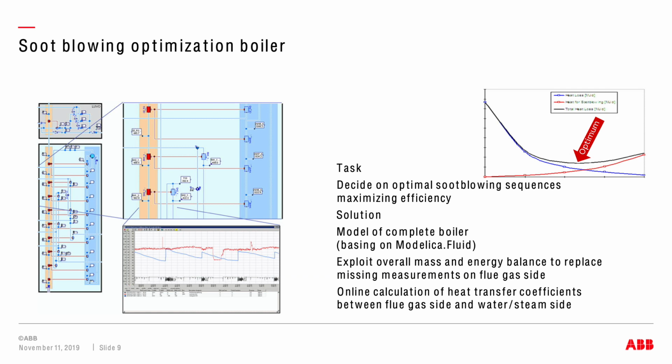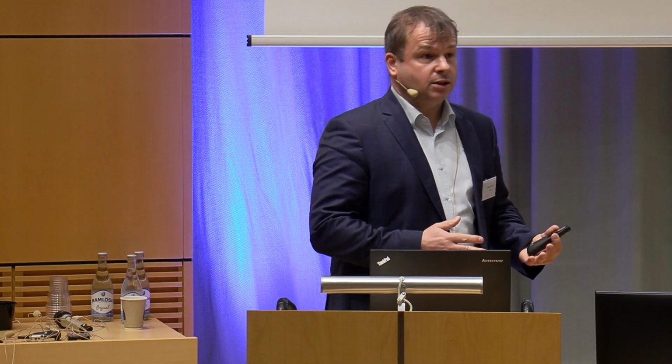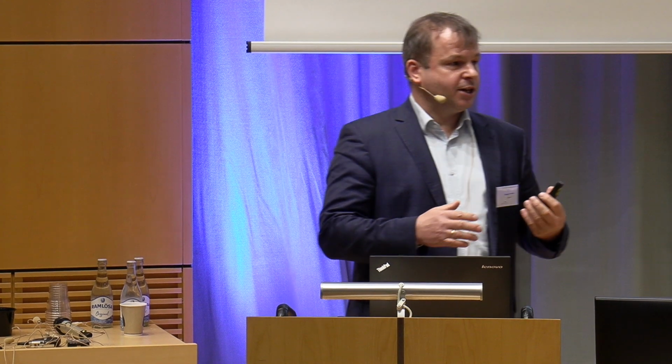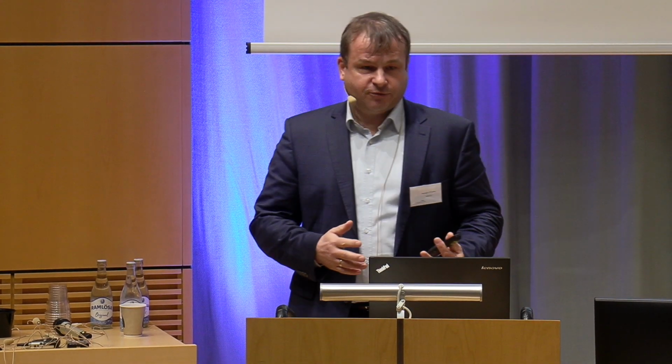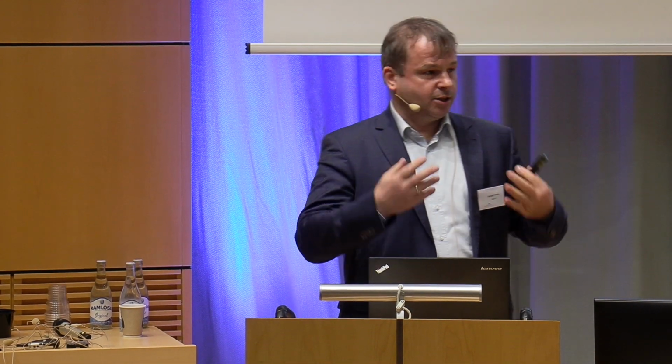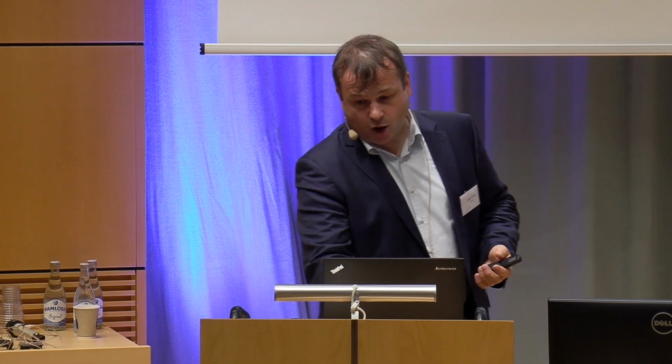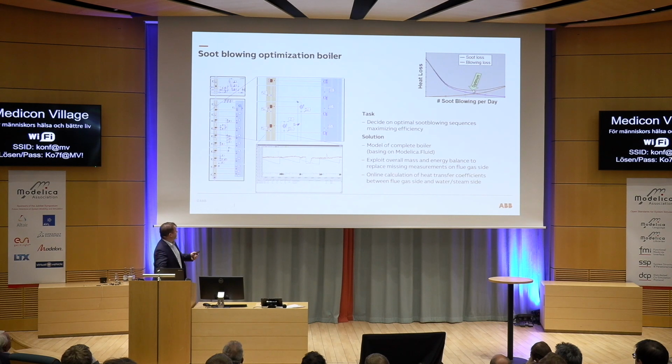If you clean the heat exchanger, you lose energy because you typically use steam for cleaning those, and the steam needs to be produced and is wasted afterwards. Meaning if you clean too much, you have a very clean boiler, but with a not perfect efficiency. If you clean too little, it's the opposite. You have so much soot in the boiler that you lose efficiency, which you better would invest into cleaning to improve the efficiency. And there is a typical optimum, how much cleaning should be applied.